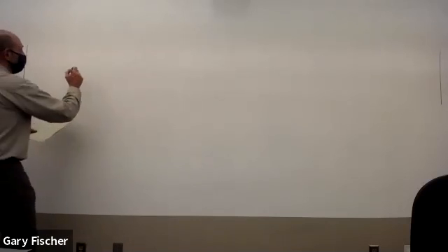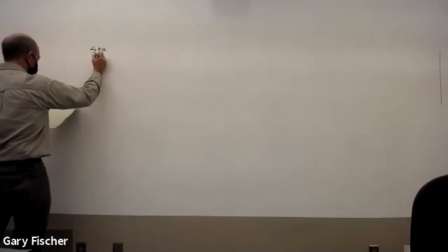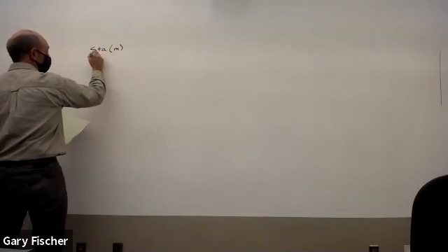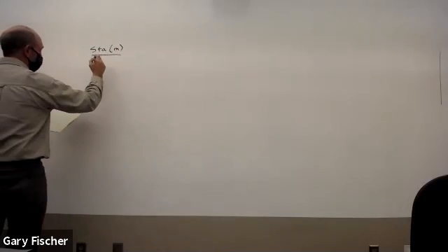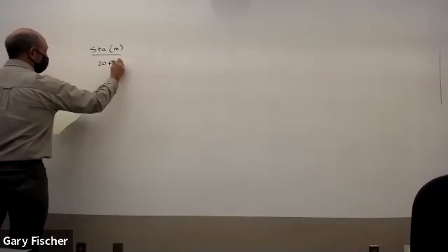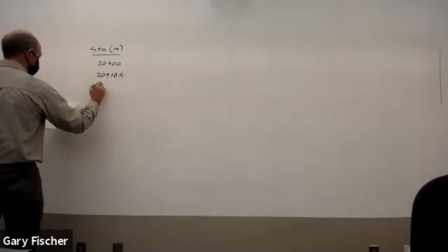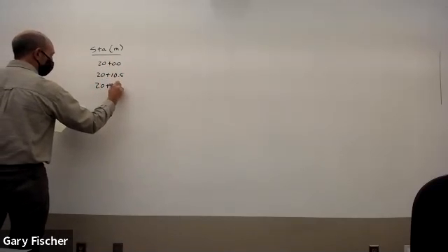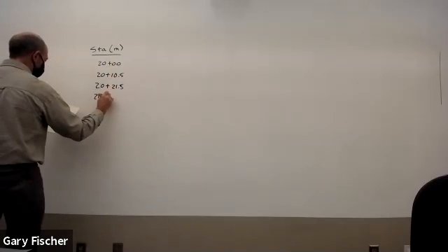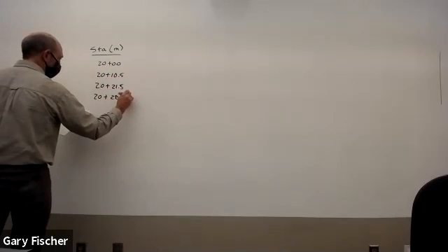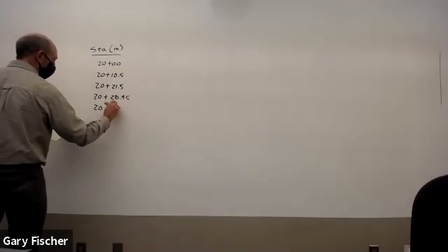This is where you would actually come up with it. Usually, when you have a center line calculation, they've got the engineering designation for distances, and it's a number plus another number. They are referred to as stations. In this problem, these are in meters, which you will never work in unless you move to Canada. The stations are: 20 plus 00, 20 plus 10.5, 20 plus 21.5, 20 plus 28.45, and 20 plus 40.